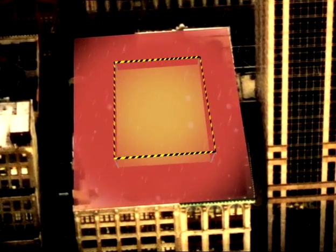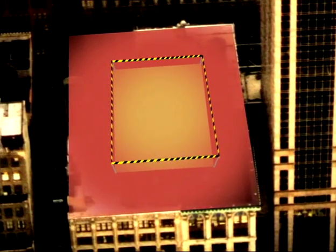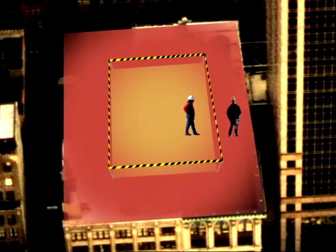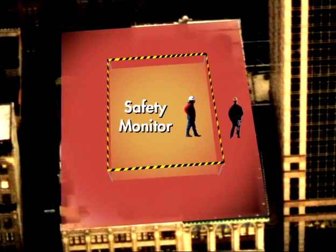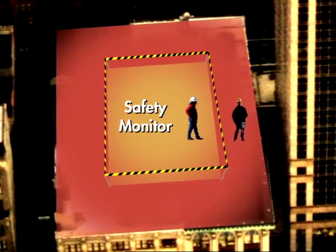In certain situations, it may be possible for work to be carried out within the control zone itself. In these situations, an experienced person must act as the safety monitor to ensure that the work is carried out in accordance with the fall protection plan.